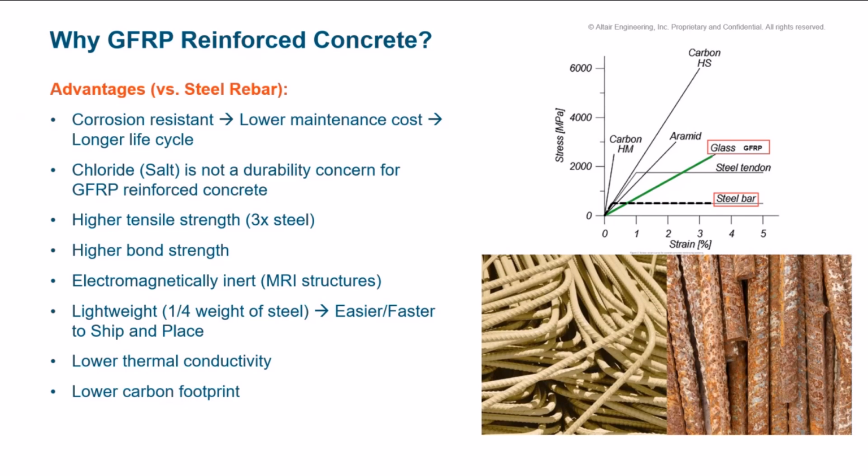So this potentially reduces or eliminates corrosion, with the inert bars not reacting, rusting, and producing cracking as steel does. The GFRP also doesn't have a problem dealing with salt or chloride, so it's actually good in marine areas near the coast with salt water used there as well.